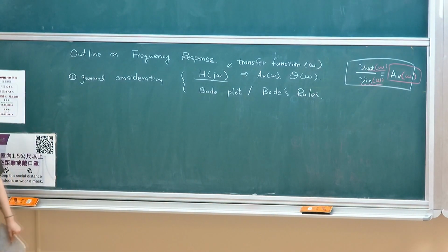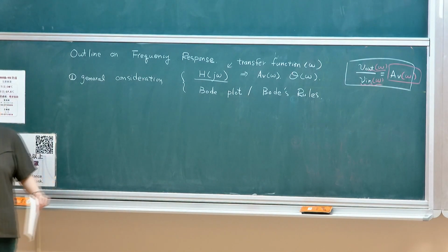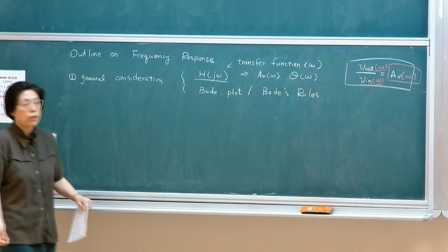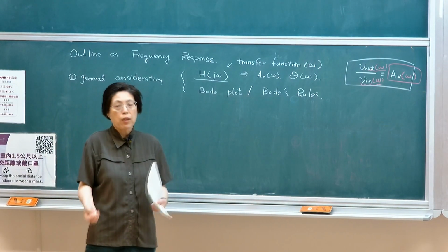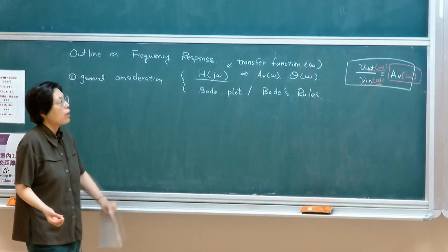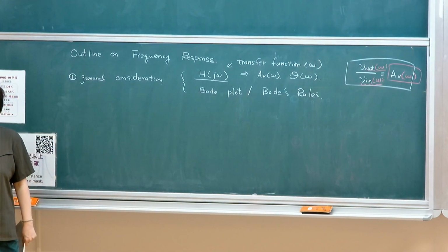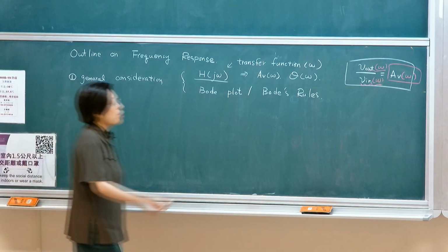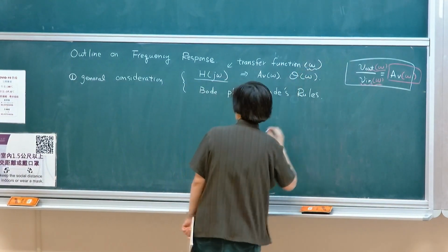So your input-output transfer characteristic, if we talk about transfer characteristic, one is that you look at input swing. Remember when we talk about transfer characteristic, you simply sweep the input DC level. That's called a function of input. But here we're talking about the transfer function as you sweep the input with different frequencies. So it's a function of frequency.